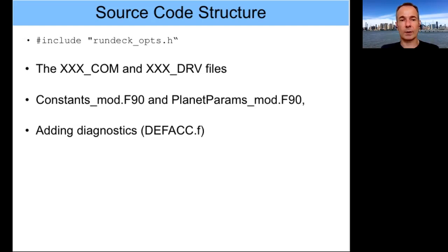The other way to do it is to think which variable resembles what you are doing. If, for example, you want to output the temperature at the 5th layer, you can see how the temperature at surface is being added, replicate that, and then make small changes to go into layer 5. I can think of nearly no cases where there is no proper example already in the code that you can follow.